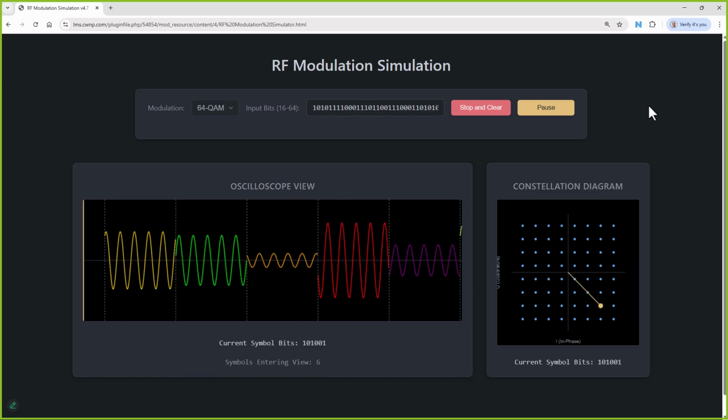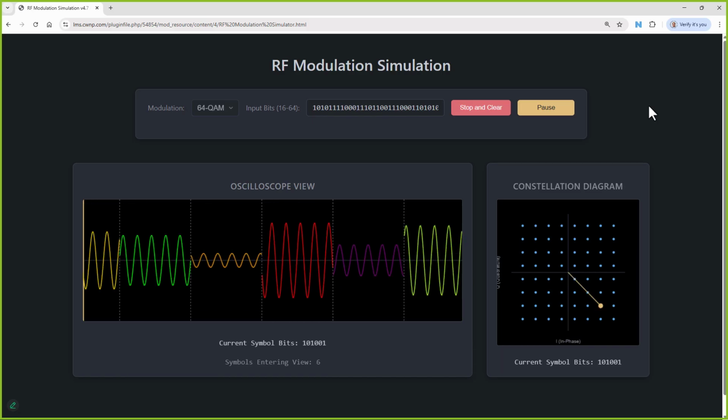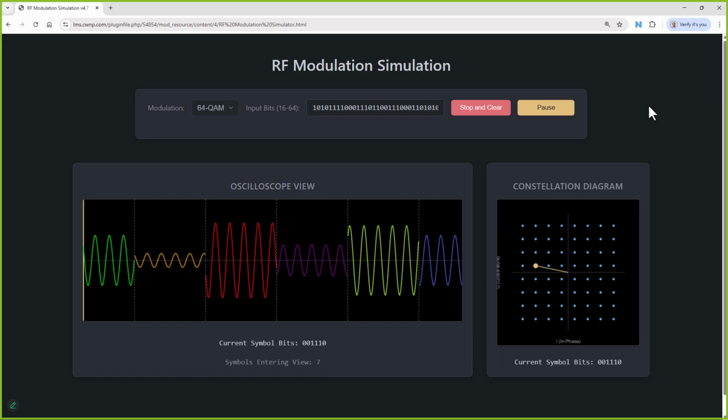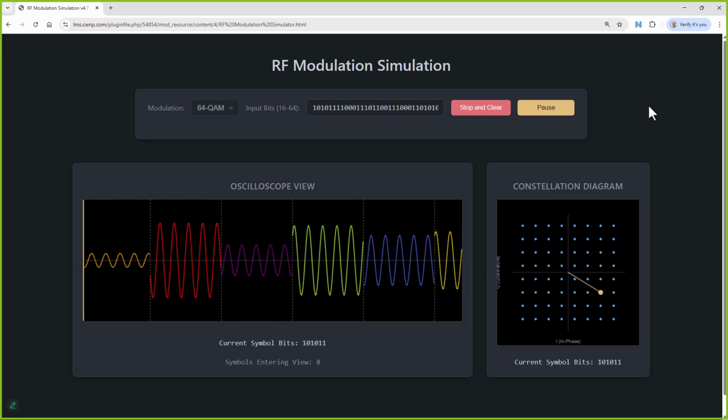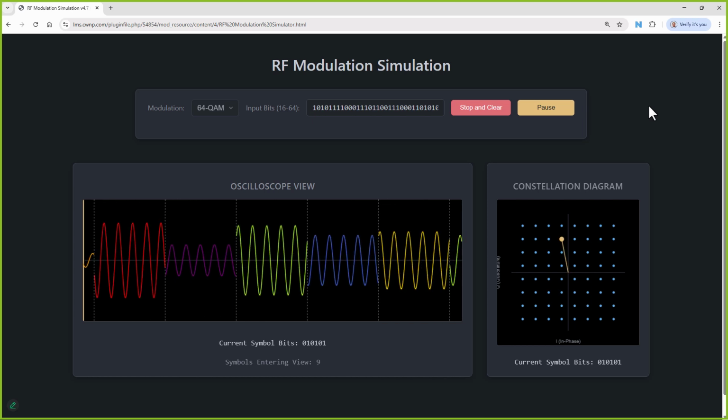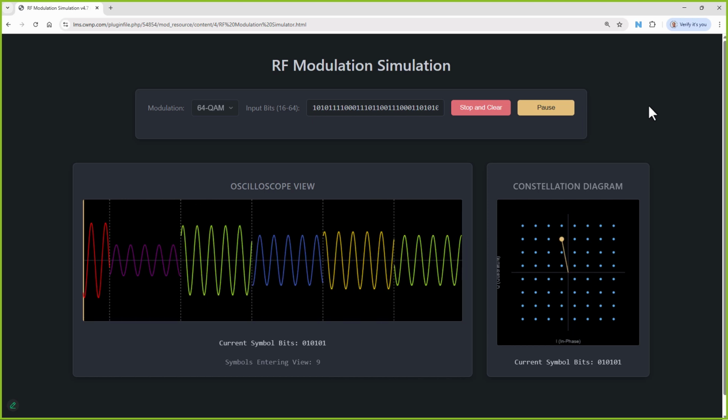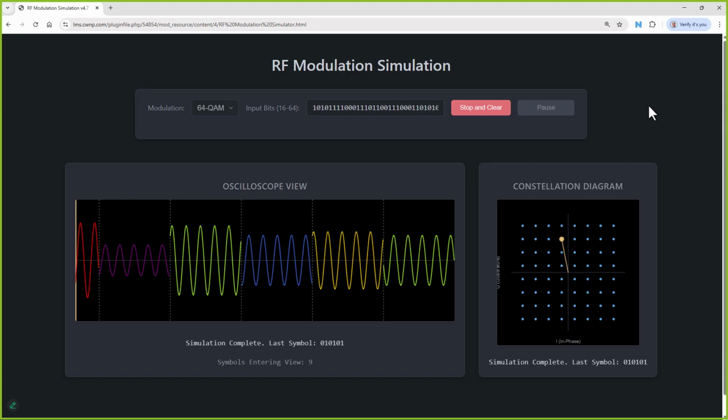Now, understanding that this is modulation is an enlightening benefit, because what it does is it helps you fully realize why you need improved signal quality to get higher data rates. So do you notice now we're pushing 6 bits per symbol through? Every time we have one of these symbol periods, it represents 6 bits instead of 4 or instead of 2 or instead of 1 bit. And so the reality is that we can go even higher, right?